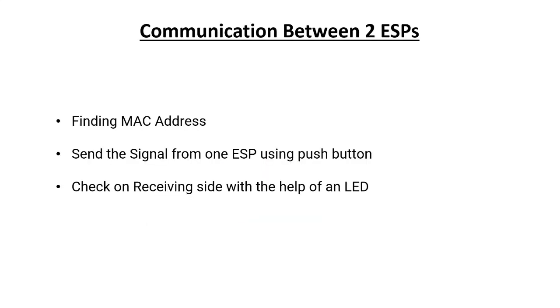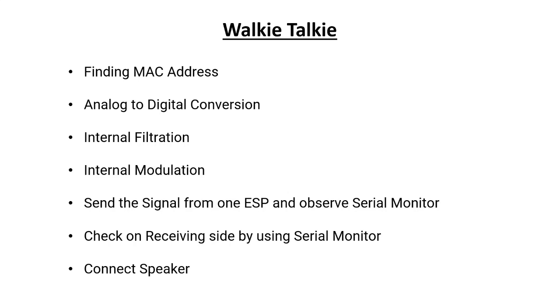Then on the receiving side we can connect an LED to see whether those pulses are being received or not. If they are pulses of high voltage and low voltage, the LED will turn on or off according to those pulses. So this is a small experiment that can tell us whether both the ESPs are connected or not via that specific protocol.